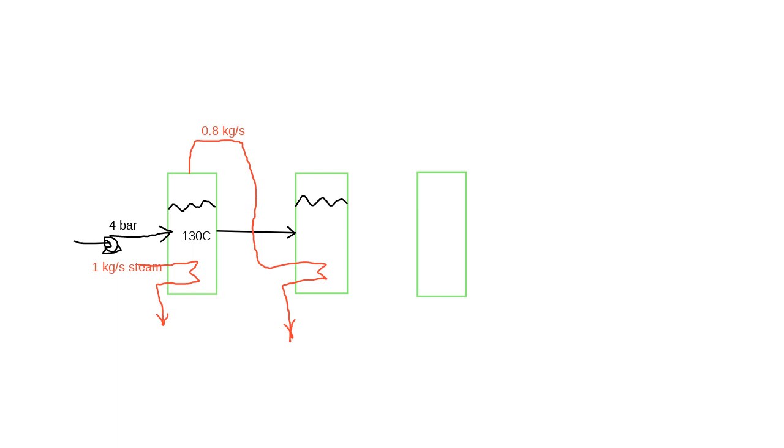So now what we can do is reduce the pressure. So we put in a valve here. Let me just get the right tool here. We put in a valve over here. Horrible drawing. Don't laugh now. That's a valve, believe it or not. And therefore, the pressure of this thing is no longer at 4 bar anymore. Let's say that we're operating this at 3 bar. I'll get my text tool in and I'll say 3 bar there.